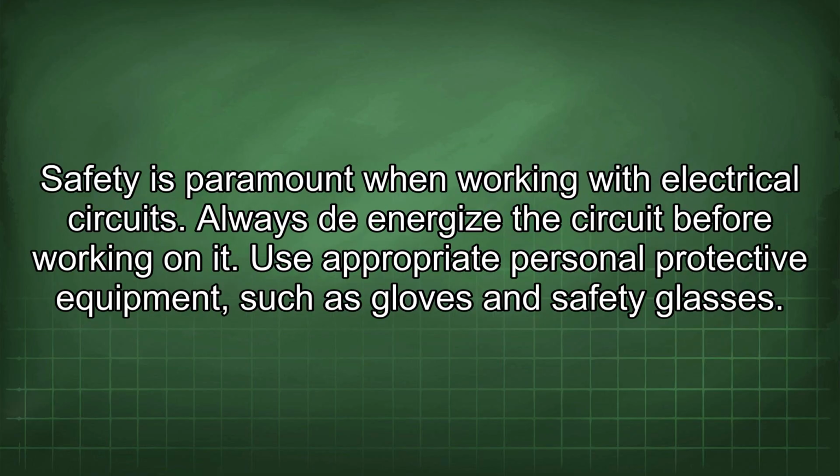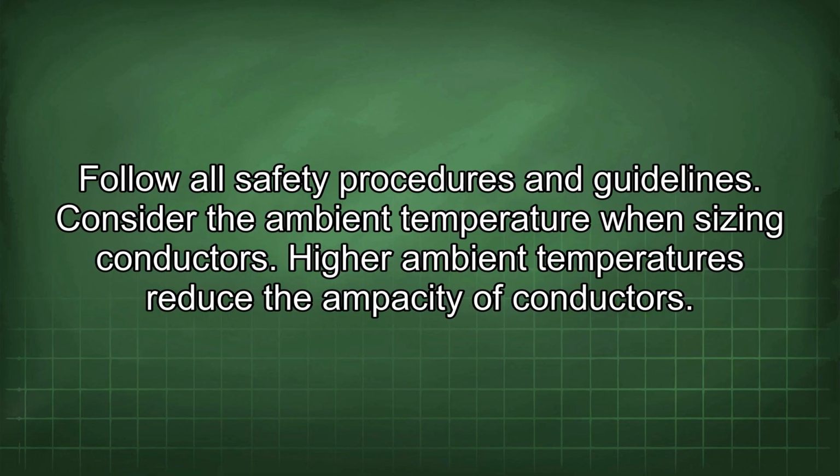Safety is paramount when working with electrical circuits. Always de-energize the circuit before working on it. Use appropriate personal protective equipment, such as gloves and safety glasses. Follow all safety procedures and guidelines.